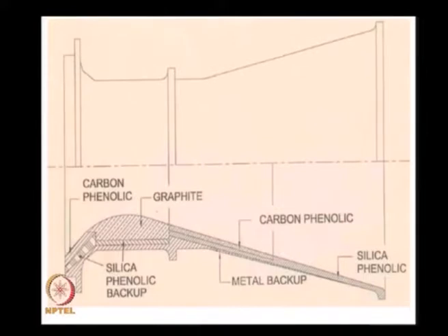It is a conical nozzle. The nozzle runs hot, therefore to protect the nozzle I give insulation on the inner surface. This is the conical nozzle. I give something like carbon which can take a lot of heat. I give something known as ablative materials. I will come back to it when I deal with cooling of rockets.